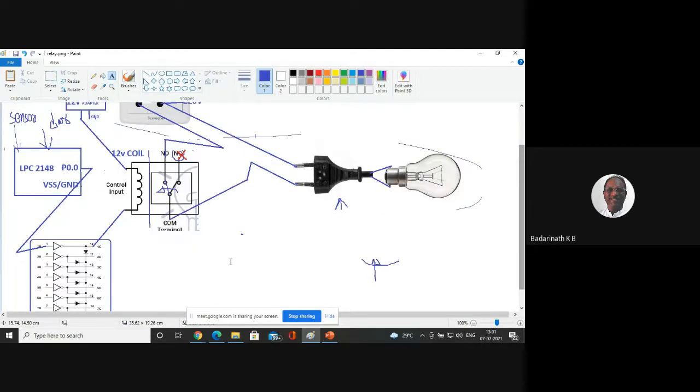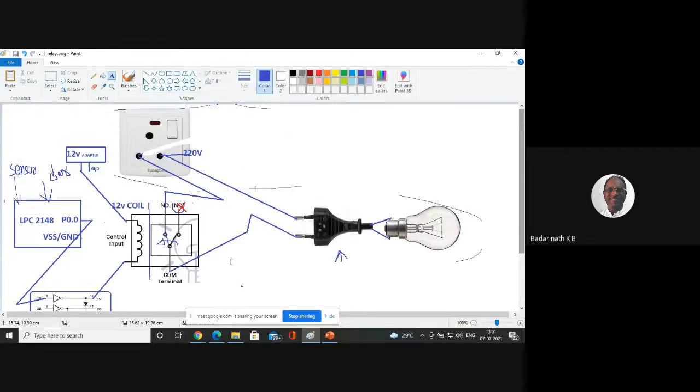So this completes how high power devices can be interfaced to the microcontroller, with the concepts of the driver IC required here, the concept of the relay, when you have to go for an electromechanical relay, when you have to go for a solid state relay, how you purchase the relay, yes or no? All these things you should keep in mind whenever you want to implement an embedded system and you want to control high power devices.